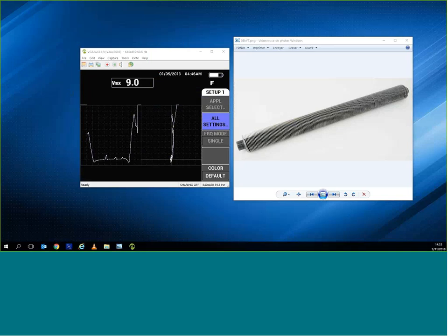By using absolute, you can actually see that the pits are not as clear as using the differential, but the absolute signal and the taper defects are really easy to see, very simple. So just knowing what kind of defect you're trying to find will help you decide which kind of adapter.